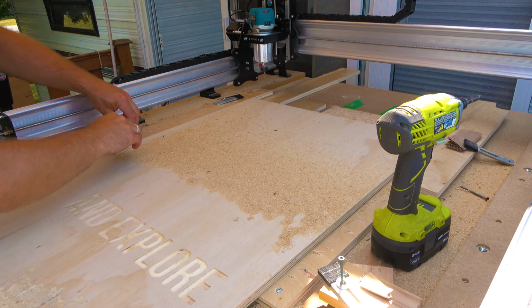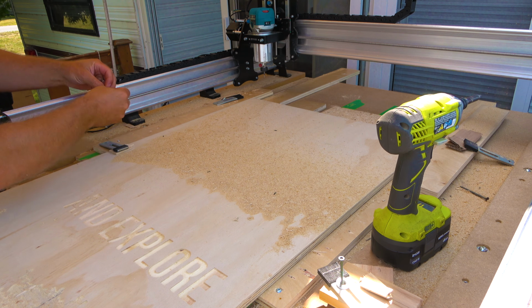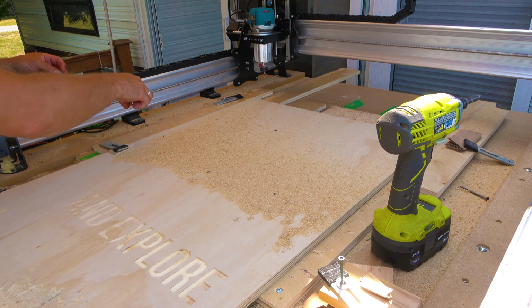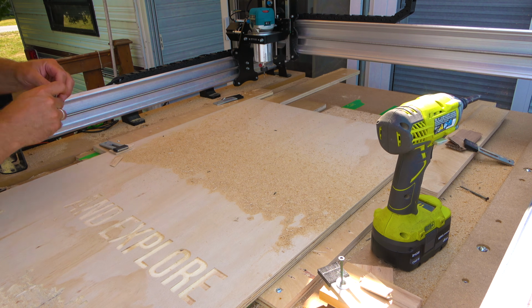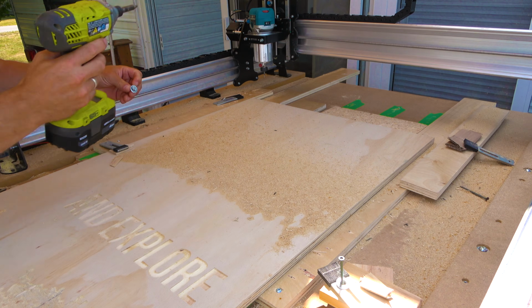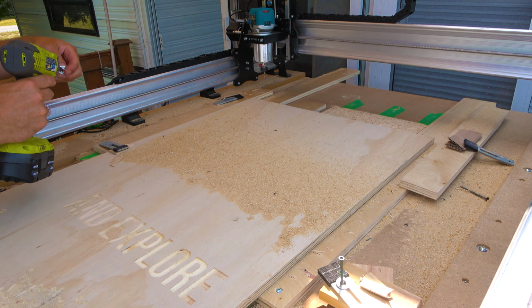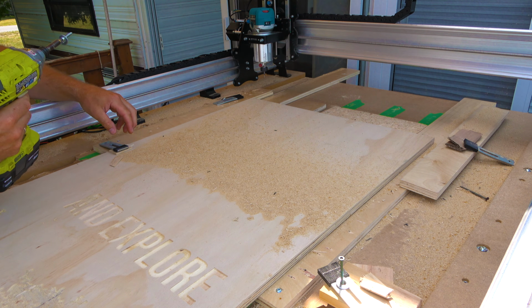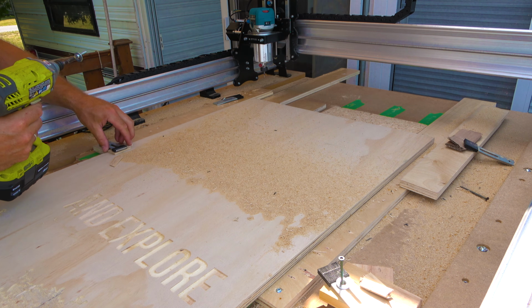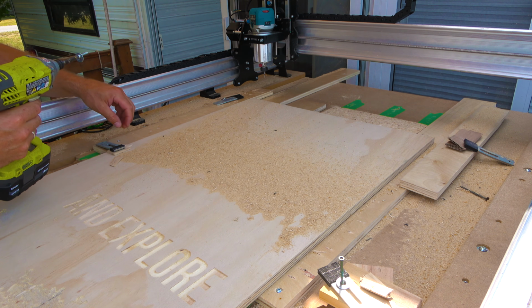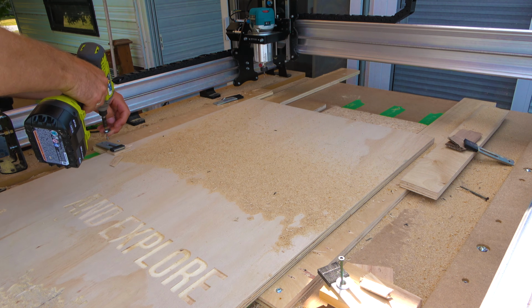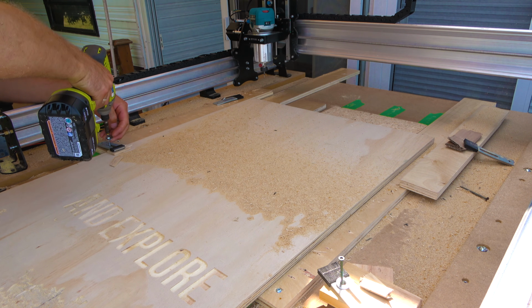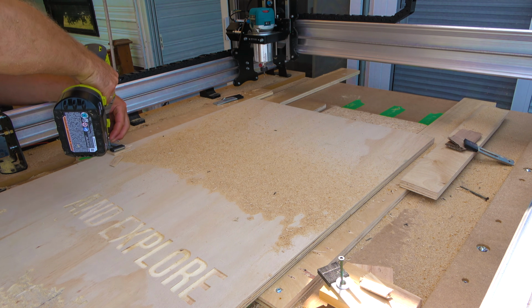On a project like this where there is no overlapping carving, it's pretty simple. If you're off by a millimeter, nobody's going to know. If you're doing a project where there is a consistent graphic, or it's a sign and letters have to meet up, then your accuracy is the trickiest part of this process, because if you're too short or too long in your slide, you will see that in the result.